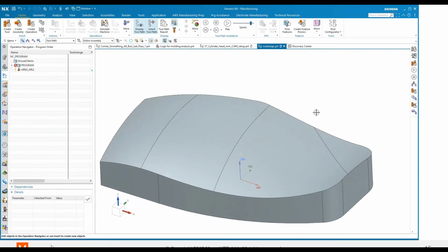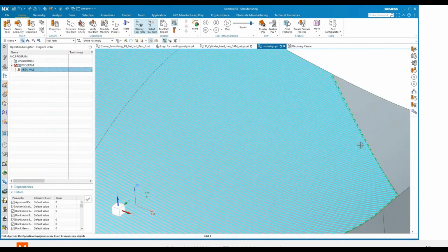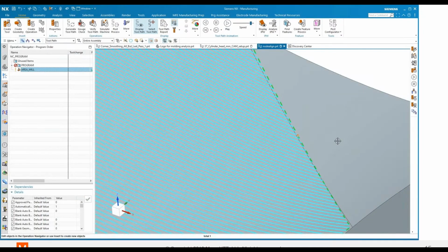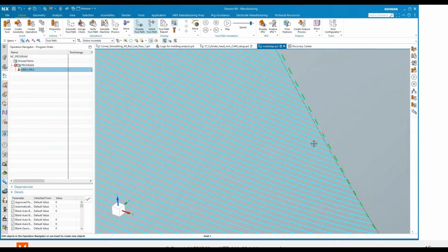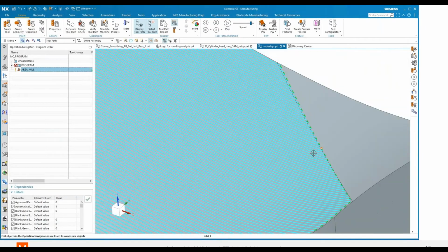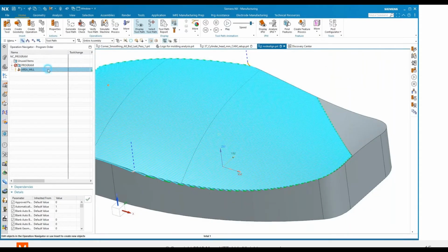Here's the part that we'll use to demonstrate our lifts on stepovers here. And you can see the problem. I'm not machining all the faces on this part. So these turnarounds here are going to potentially leave a divot on the surface that's going to be hard to clean out with hand finishing. So let's make a couple changes and solve this problem.